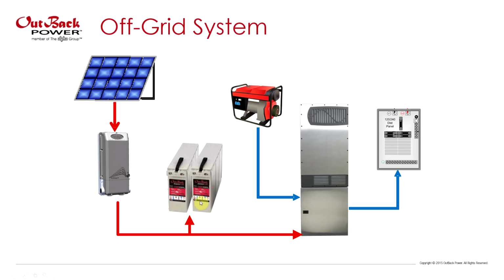So this is our DC bus. Next, we have the inverter, which is a DC to AC converter. But like I said, our inverters are able to also charge our batteries, so it also is an AC to DC converter as well. And that outputs AC power to our subpanel.